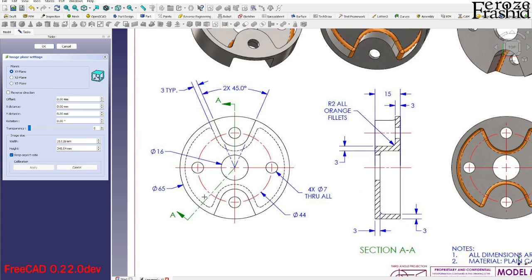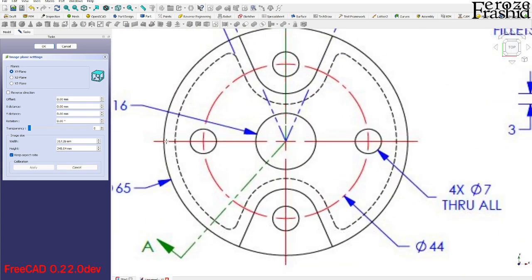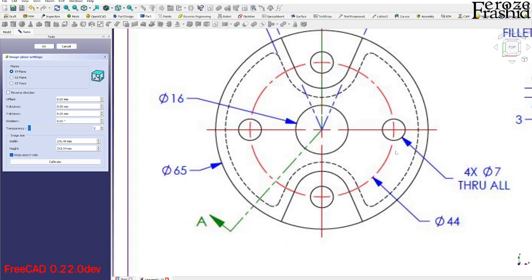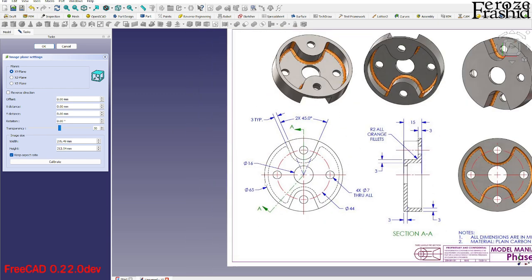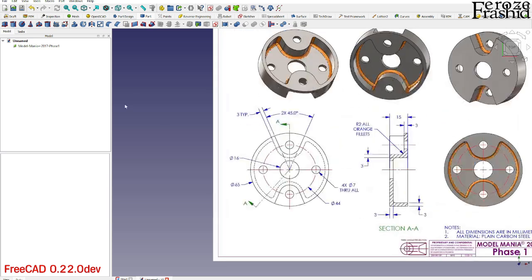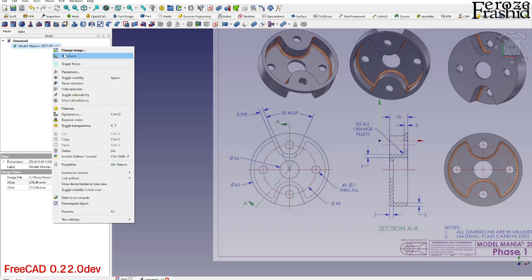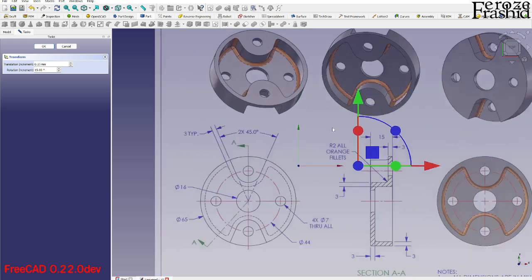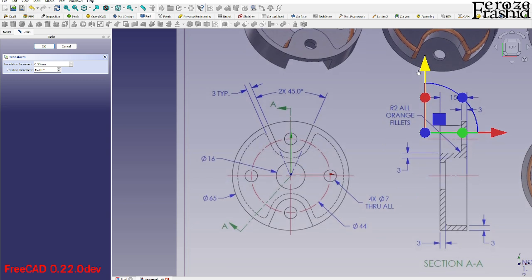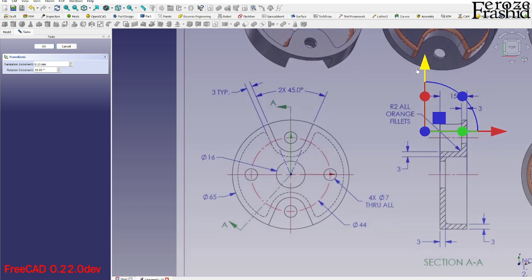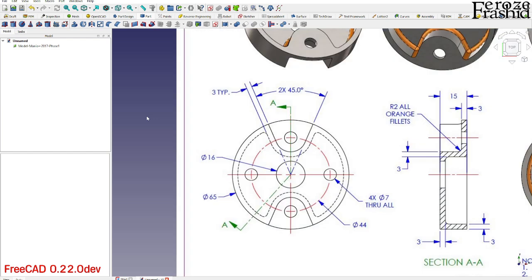I obviously want to use this to my advantage during sketching. This is diameter 65. Let's make this half transparent and keep that on the XY plane, because this is the diagram that I will be using. And let's see if we need to change the center of the image to the center of the workspace. There. Now it's all ready.